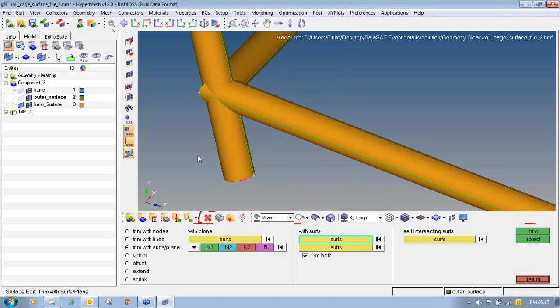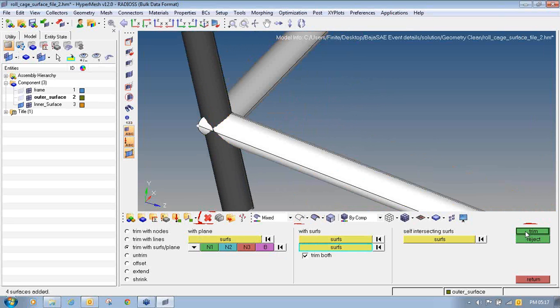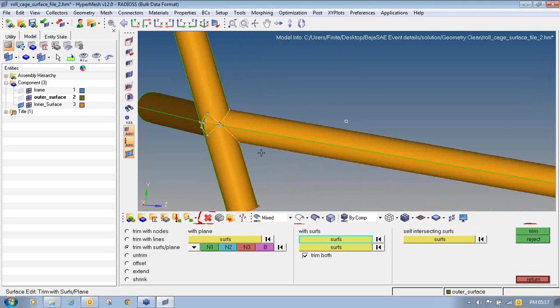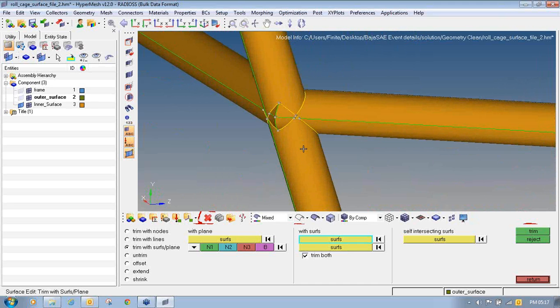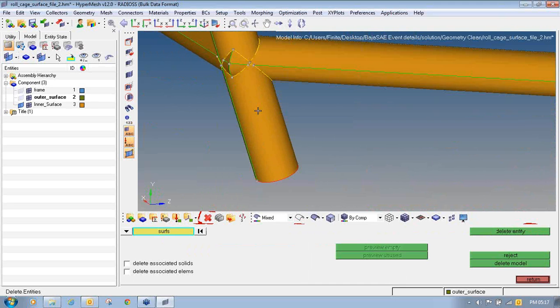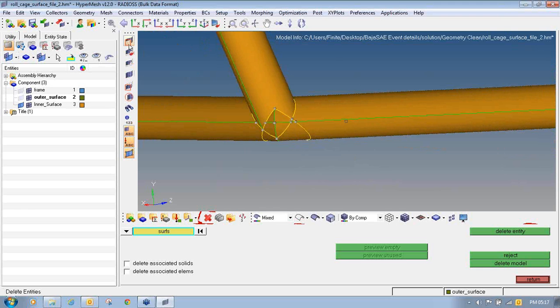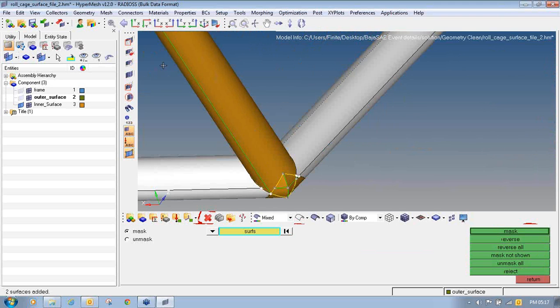Select this second panel surfaces first option. Then click on second option and select both these surfaces and say trim. Once you click trim, it will split both the surfaces and connect it. Then again I will click on F2, delete this surface, then click on F5, mask all the surfaces which I want to capture or retrieve.